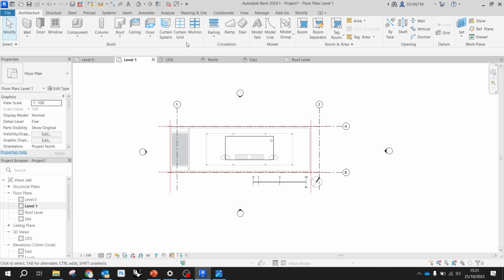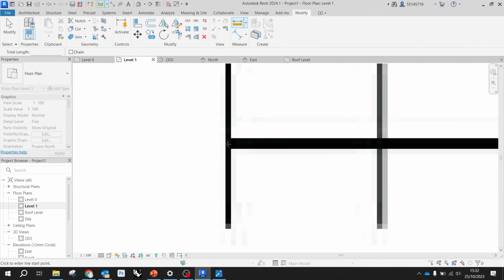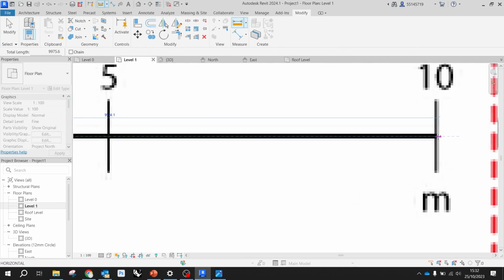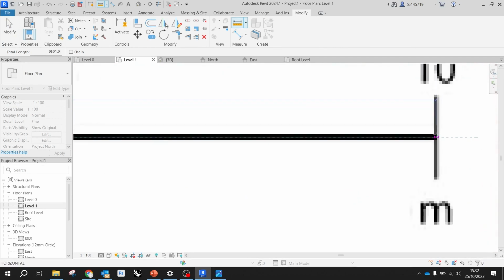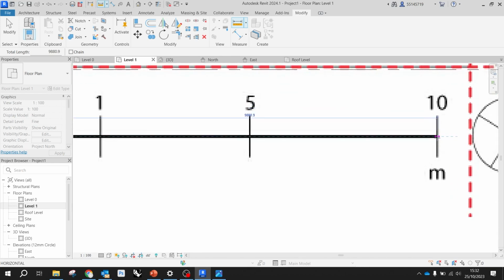Sorry everyone, let's do this check together, because walking around I noticed some of you still don't have it at the right scale. To double check the scale, you can use the measure between 2 reference tool, which is also found under modify. Click on the first reference point, which is going to be 0, and then the second one, here where it says 10. If it's close to 10,000, you're at the right scale. If it's like 5,000 or 50,000, definitely not the right scale, so we need to scale it again.